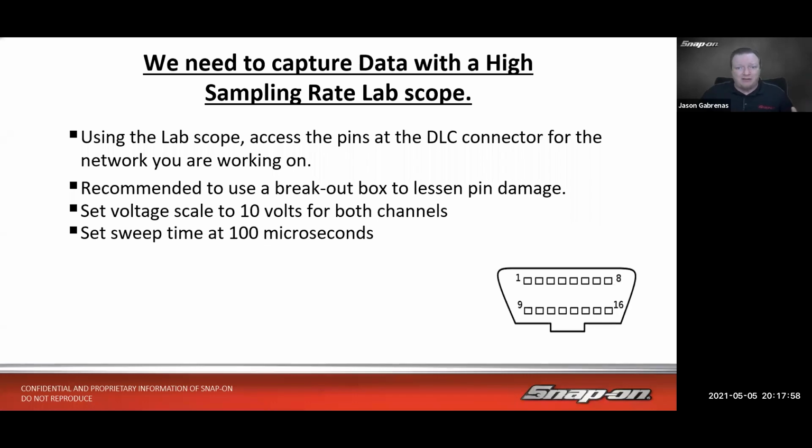And then we divide as we add channels. So we do 2 channels, it's still 3 million samples per second, 3 times faster than we need to sample in order to catch a 1/1,000,000th of a second glitch. So we're in good shape there.